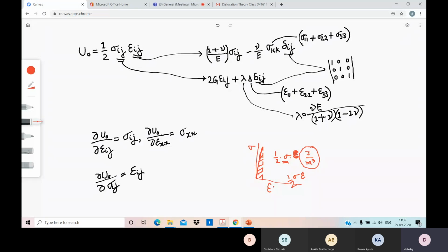But now actually you know sigma is not a single sigma. The sigma that we express in a tension test is basically your principal applied stress, sigma Roman 1. And the strain that we measure is basically the epsilon Roman 1, the principal strain. With respect to the cross-sectional plane, it is basically your principal plane on which the maximum principal stress sigma Roman 1 applies. On the other two principal planes, there is no stress, Roman 2, Roman 3 equal to 0.